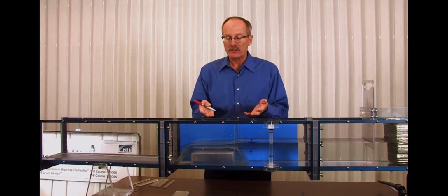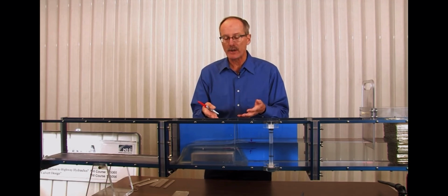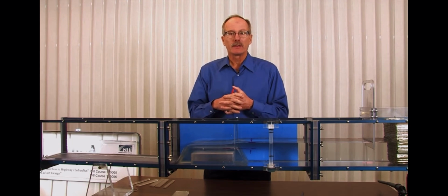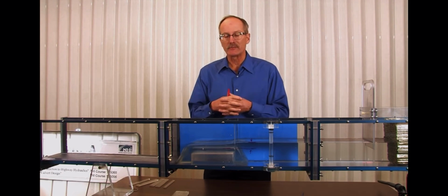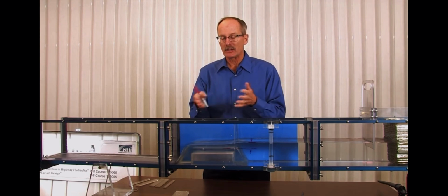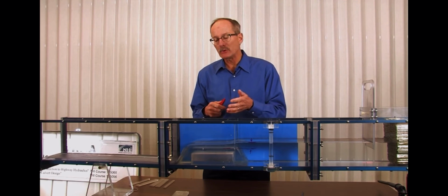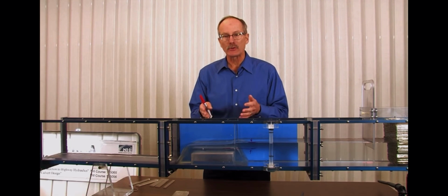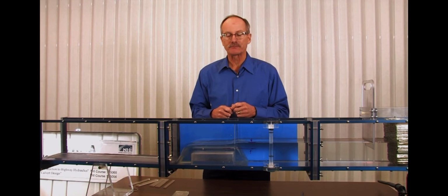We can apply the equation, and we do this a lot in our training course classes. Take these measurements, we apply the equation, and it's actually quite remarkable using a C sub D of 3. You can look up a C sub D value for different weir types, and for a broad-crested weir, 3 is a reasonably good estimate. There's a small range on that number depending on conditions on the weir crest and submergence, but 3 is a good place to start. When we do that, we get a discharge that's very close to the known pump discharge that I'm running right now, which is about 0.05 CFS.